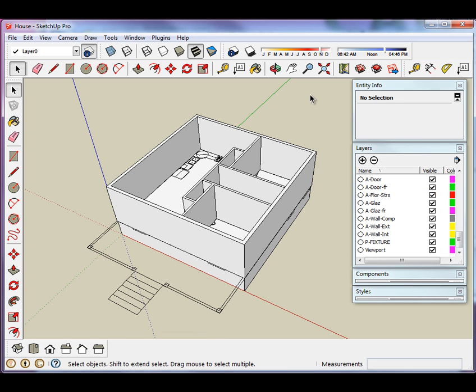All right, now we're ready to talk about the roof. We're actually going to use a plugin to help us with the roof. We're going to start designing a craftsman style roof for our cottage. So one of the first things we want to do is outline as a plane the area that the roof will cover. And separately, using the settings of the plugin, we can define what the overhang for the eave will be.